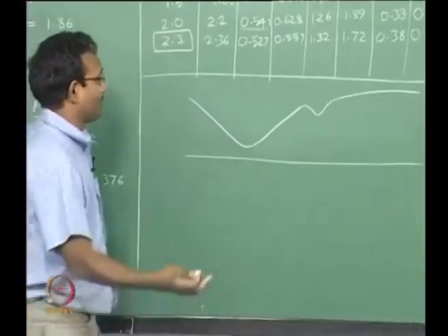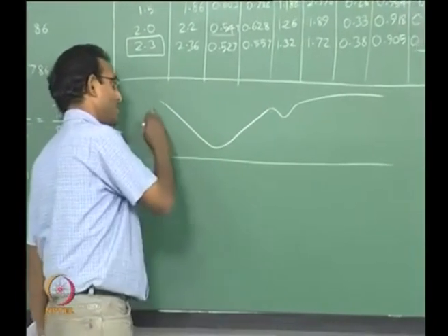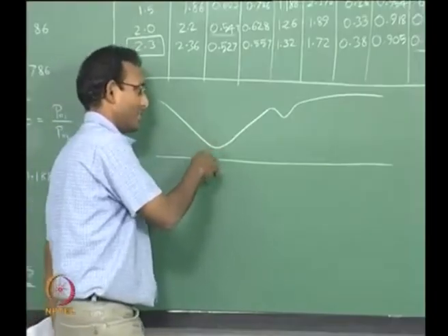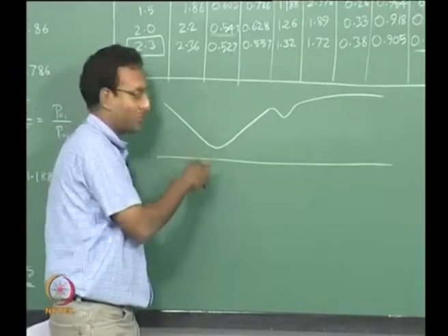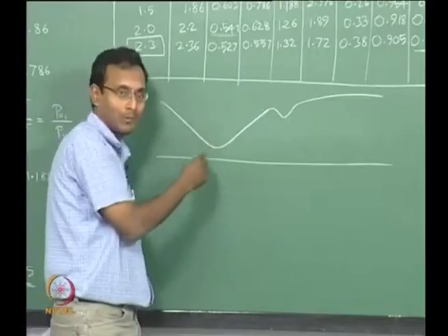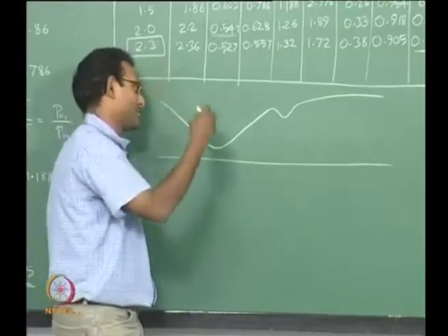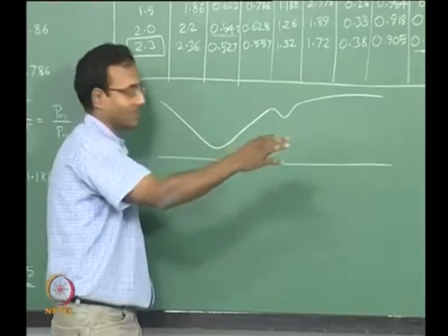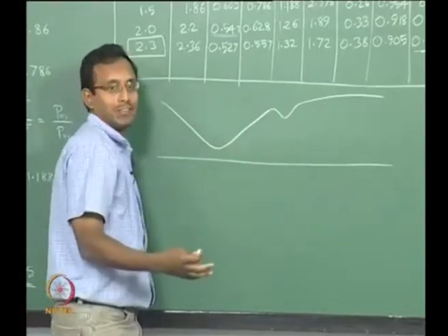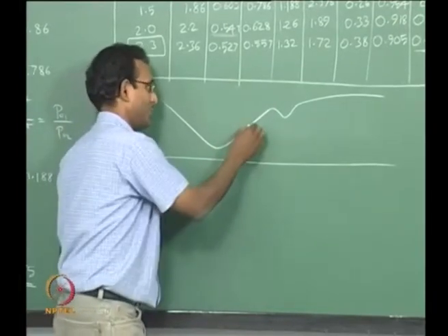How will I solve this problem? If it is a fully subsonic solution, I am going to say it is going to go through as A by A star, I am assuming it is choked here. If not, you can also solve the problem similar to what we talked about last class towards the end. The same procedure can be applied here. That is not interesting enough. So, we will go to a case where there is a shock in the divergent section,